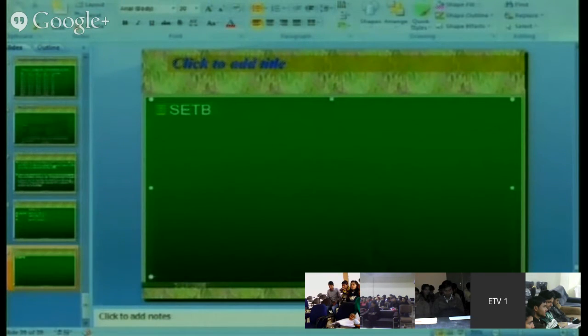I will write SETB, which is the bit P2.3. Okay. And then what should I do? What is the operation which I'm going to do? We are going to continuously monitor this bit. And in case it is high, I have to send a high to low pulse. So if I make it such that till the time it is low, keep it here, and if it becomes high, go to the next step. So tell me.